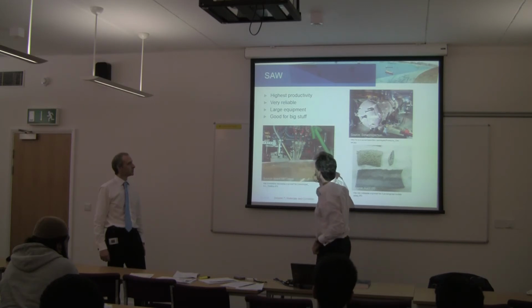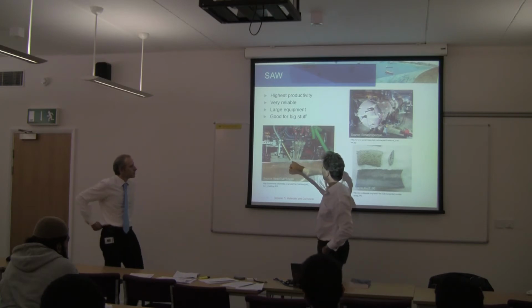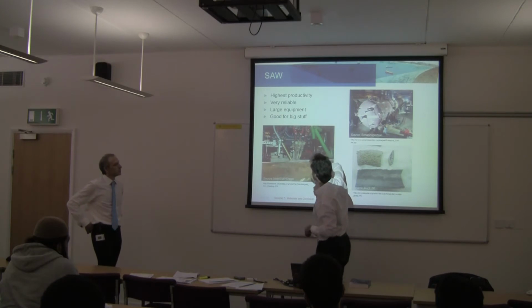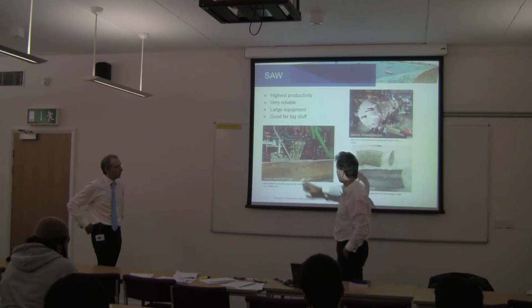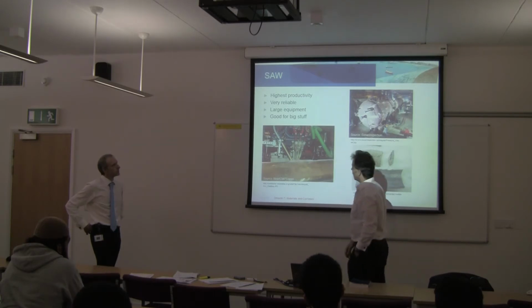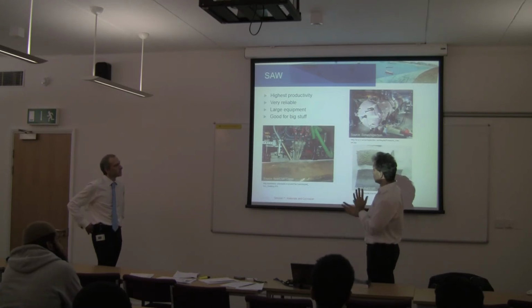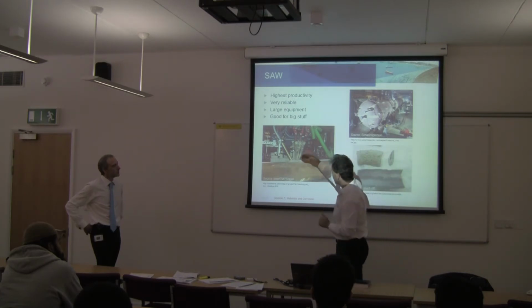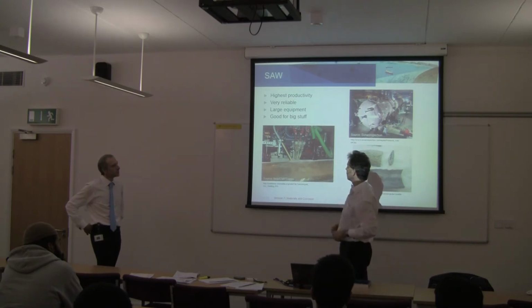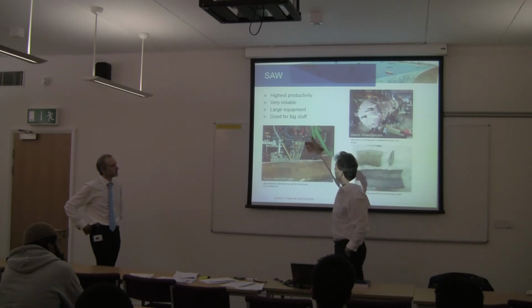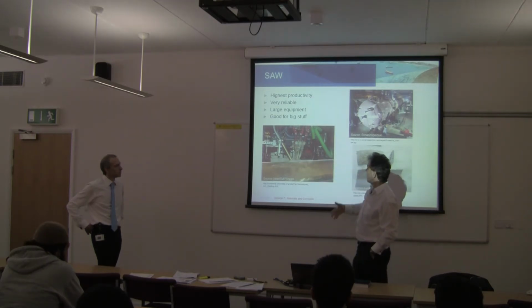So this is submerged because they are submerged under the flux powder granules. It's actually a complex machine with 3 wires coming down here, and each one has an electric arc struck off, and it's all hidden under this blanket under the flux. You've got a nice controlled pool of metal melting a bit into the plate metal. As the welding head progresses along, the temperature decreases behind and the metal solidifies. With the control of the chemistry of the 3 wires coming in, and the control of the chemistry of the flux, you get the right chemistry of the metal.